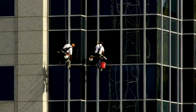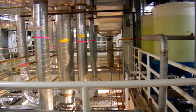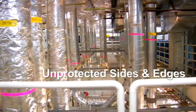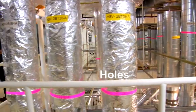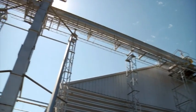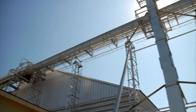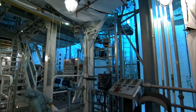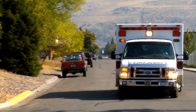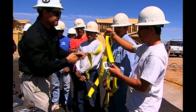Anytime an employee is working 4 feet above a lower level, fall protection must be provided. The 4-foot rule applies, but is not limited to unprotected sides and edges, hoist areas, holes, and runways or similar walkways. OSHA allows employers the flexibility to select and provide the fall protection they determine will be the most effective in the particular workplace operation or situation to protect their workers and prevent injuries and fatalities from occurring. Employers can choose from a number of protection options.